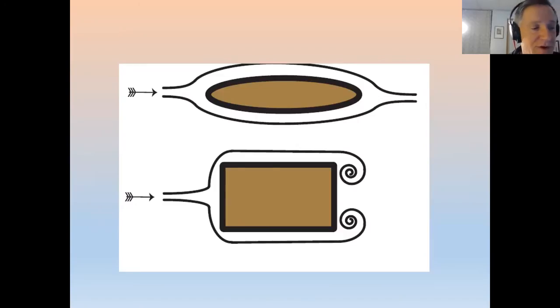The bottom boat is a barge, so the water comes up and smacks it at the bow and then goes around the bow and then creates these eddies behind it. Well, you can intuitively imagine these eddies produce a low pressure, and this impact at the bow produces a high pressure. So this pressure difference between the bow and the stern is called pressure drag. So that's the pressure across this bow. So high pressure here where my mouse is, low pressure here.